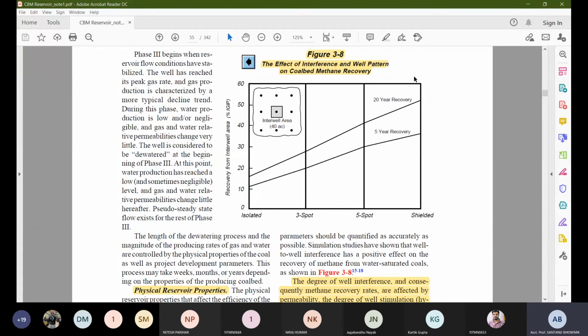As you move from the central point of the borehole into the rock, after some 3 or 4 times of the borehole diameter, you will find that there is no such disturbance. But then this distance of 3 to 4 times the borehole diameter may be significant, because in the other part there is another borehole lying.